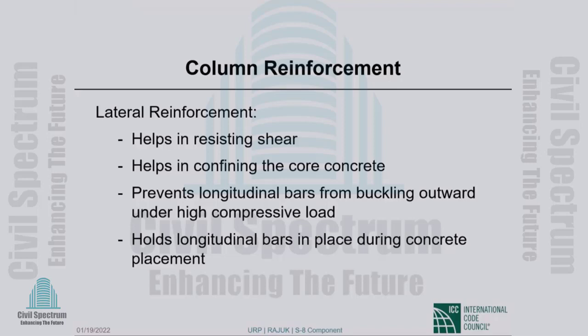If you confine concrete, particularly tightly, it gains strength, but that is not the main thing. The gain in strength, while substantial, is not huge. But the concrete now is, I would use the word, ductile.